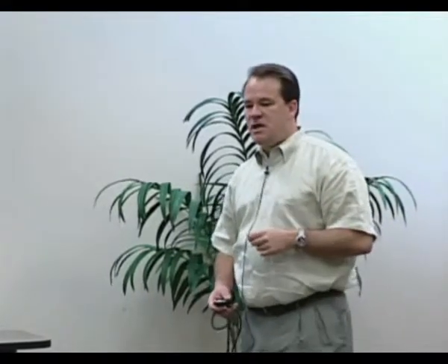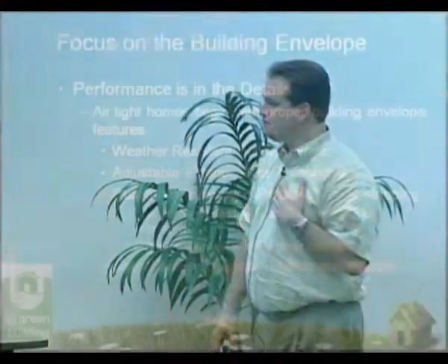Build tight, ventilate right. People are always concerned, can you build a home that's too tight? The answer is really no. The tighter the better. You bring in mechanical ventilation to control the amount of ventilation within your home rather than relying on Mother Nature to determine when you're going to get air into your home and when you're not. Very important. We'll briefly talk about some insulation types and techniques, wall system design, and home plan design.